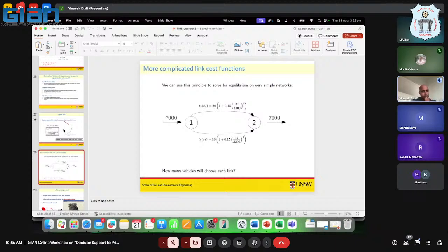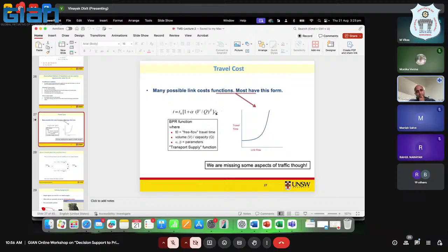Yeah, no, this is where I wanted to go down here. So alpha, beta, and Q, right? The capacity. So capacity is, if you've got a 1-lane road, generally it's 1,200 PCU per hour, right? Then you multiply that by the number of lanes, you get a Q. Or you choose your alpha and beta, as alpha is 0.15, beta is 4, and then you play around with your Q. So what you're trying to do is, given an OD table,